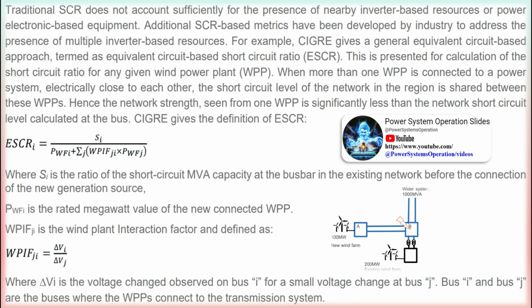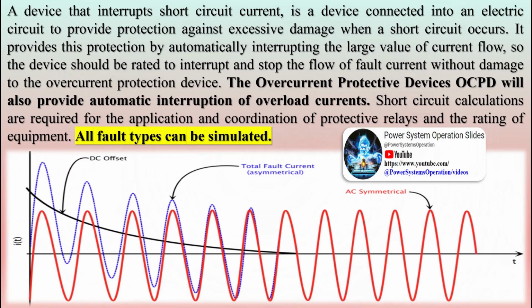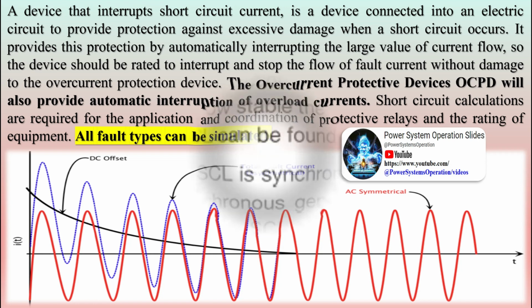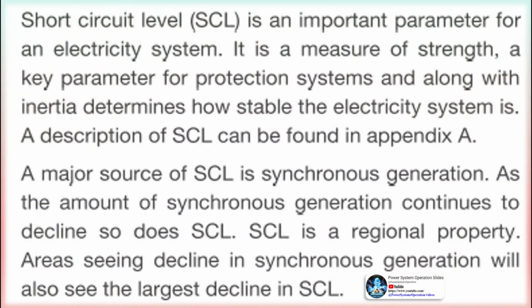Short-circuit currents impose the most serious general hazard to power distribution system components and are the prime concern in developing and applying protection systems. Fortunately, short-circuit currents are relatively easy to calculate. The application of 3 or 4 fundamental concepts of circuit analysis will derive the basic nature of short-circuit currents. These concepts will be stated and utilized in a step-by-step development. The 3-phase bolted short-circuit current is the basic reference quantity in a system study. In all cases, knowledge of the 3-phase bolted fault value is wanted and needs to be singled out for independent treatment. This will set the pattern to be used in other cases.